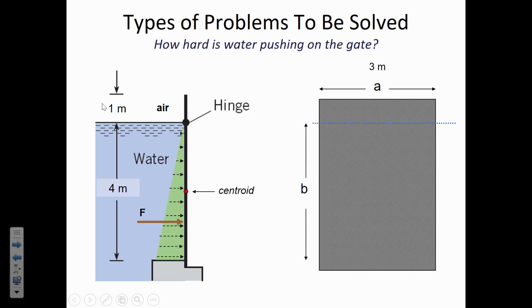So it's easy, just by inspection. The centroid that we'd be interested in doesn't take into account the full height of that plate. It would just be the submerged portion where water is in contact with the plate. So you'll notice that this dimension B doesn't go down to the bottom edge of the plate. It doesn't go to the top, and it doesn't go down to the bottom. The reason it doesn't go down to the bottom is it's only referring to that portion of the plate that's receiving pressure from the fluid that's touching it.